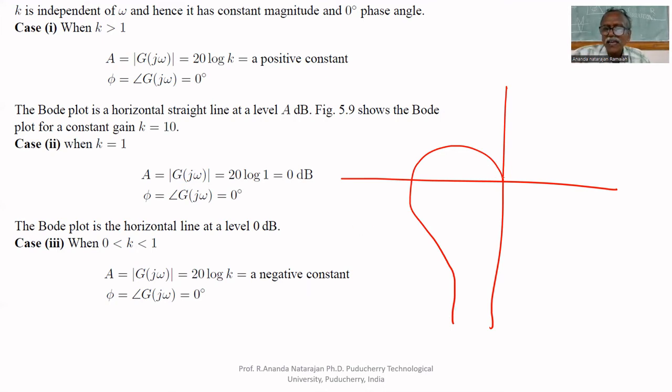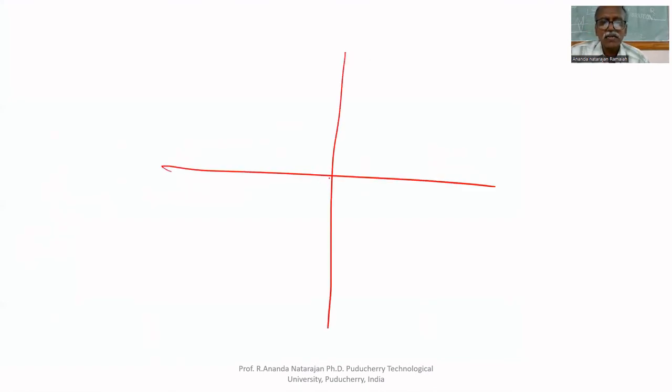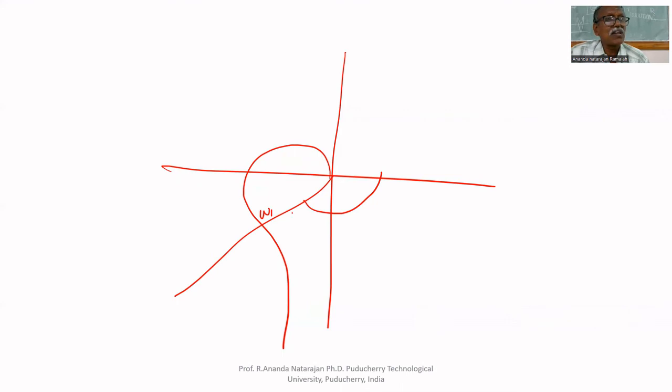If you increase the gain, it amplifies like this. So if you increase the gain, it becomes unstable. Now I am not increasing the gain, but I am increasing the phase shift. What happens if I increase the phase shift? For example, this is the system. The phase shift for a frequency omega 1, say, what is this angle? Up to this, 90 plus 45, 135. So we can say 135 degrees at this point.